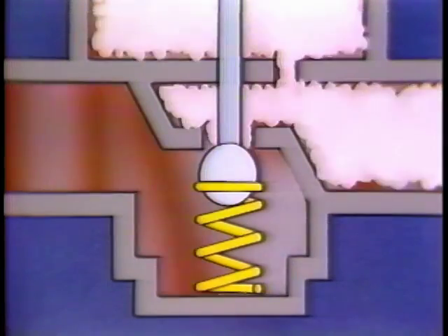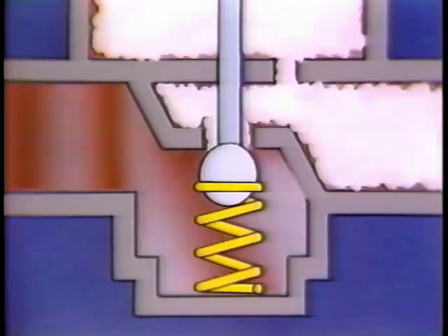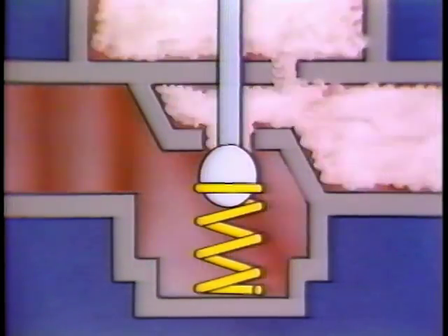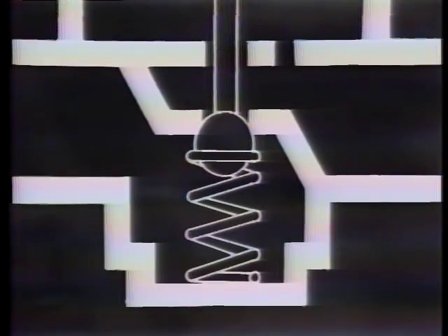In either case, since gases are compressible, unlike liquids, there is a cushioning effect, so water hammer is not a problem. If the fluid is steam, its erosive nature dictates metal seats and valve plugs. Greater force is needed to seal the metal-to-metal contact. This is best provided by using an unbalanced pressure valve with the valve opening against the flow.